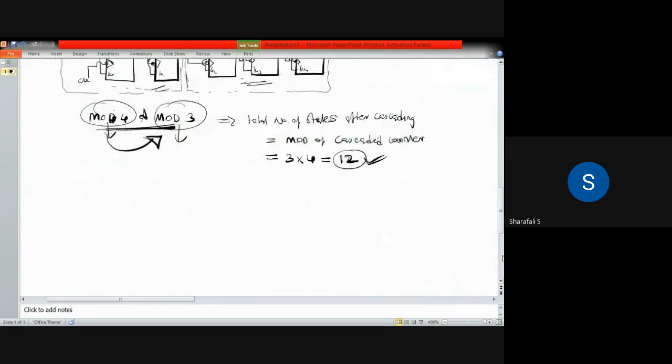I will just say, if you have this mode 4 here, which means we'll have two flip-flops, a 2-bit synchronous counter, and we'll have the mode 3 counter here. For mode 3, we need an additional NAND operation and all those things that we discussed in the last class. We connected this.